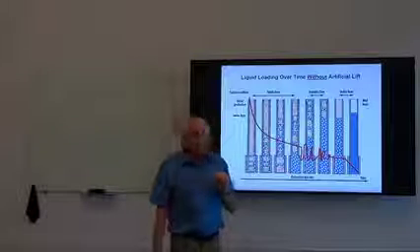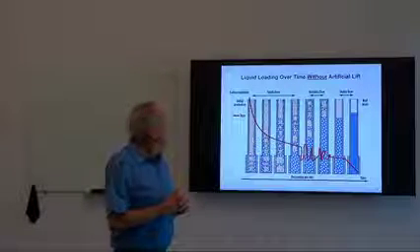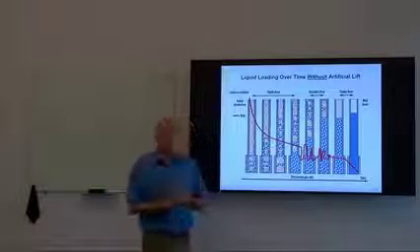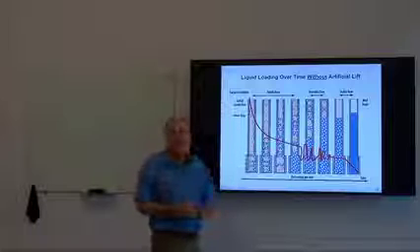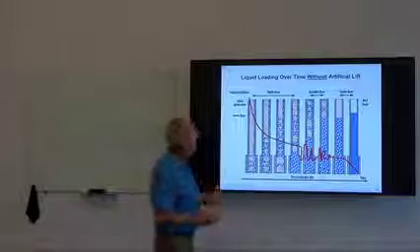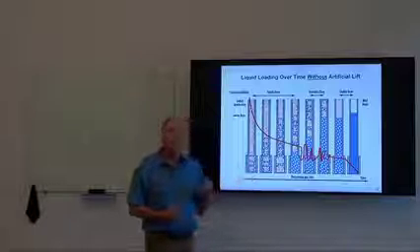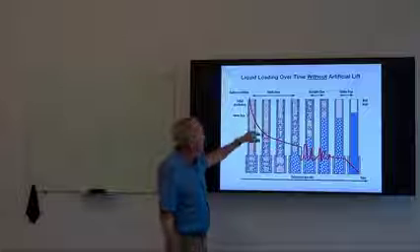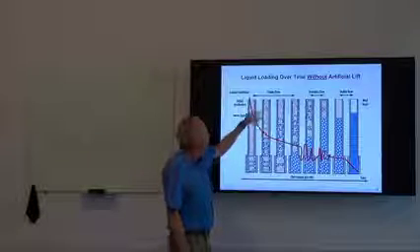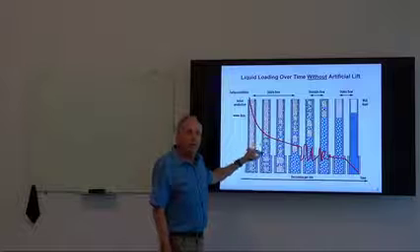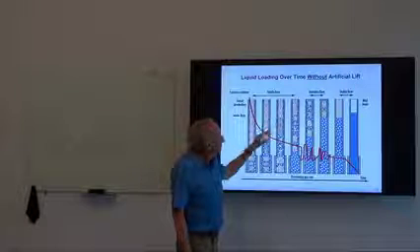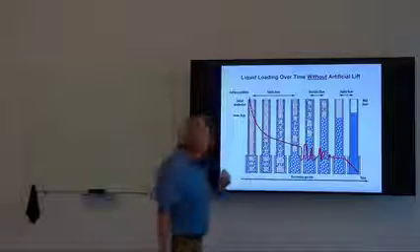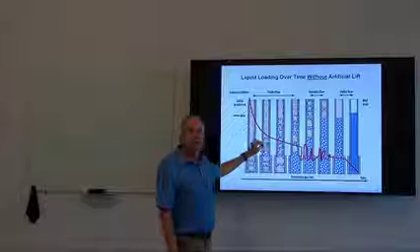I started to talk earlier about the accumulation of liquid. And that accumulation of liquid occurs for two reasons. We have gravity, of course, which is trying to hold the liquid down in the well. But the primary thing is we do not have sufficient gas velocity. So our gas velocity here is very high. Here we see we have high gas velocity in the upper part of the well, but a lower gas velocity down lower. And that is what becomes progressively worse and worse. And it's important to understand that there truly is a difference in velocity.